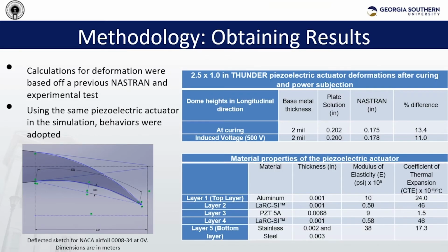With all of the original airfoils simulated, I proceeded to remodel them to have the piezoelectric actuator applied at the trailing edge. And you can see a little bit of this for airfoil 000834 on the left here, where this portion right here was the original airfoil as it proceeded at the trailing edge. And down here you can see a dome applied. This line right here represents the piezoelectric actuator at its deformation stage.